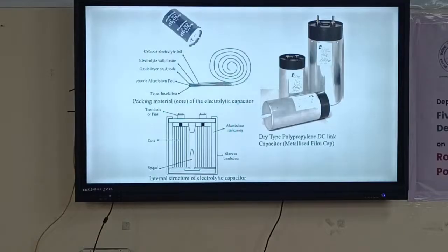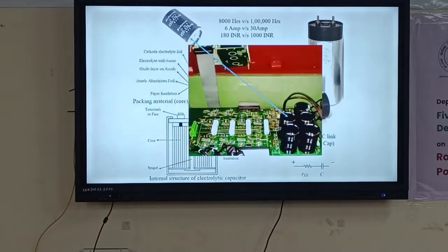And then we use such a bulky capacitor. You know, most of you, some of you work in electronics, so you must have seen tiny ceramic capacitors. They are good for the signal level. But in a power converter, we require this type of bulky capacitors. For example, 450 volt, 470 microfarad electrolytic capacitor, the screw-terminal type capacitor. So using these components, we fabricate the power converter. Okay.